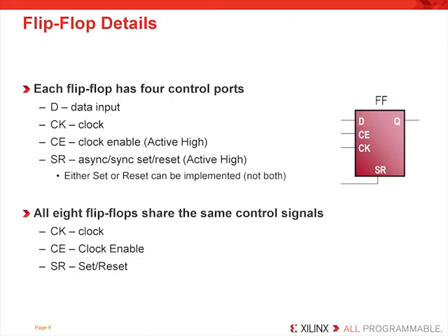The set reset port can also be implemented as asynchronous, although this is not as flexible. An asynchronous set reset port cannot be implemented as a LUT input, so your synthesis tool and the implementation tools don't have the ability to map this control signal to a LUT input. You should always remember that clocks and asynchronous sets and resets always get access to the control ports.